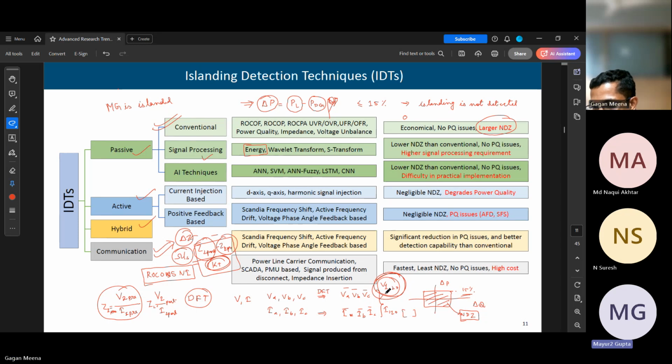Especially under frequency protection is there everywhere, because the grid has a plan for how to manage if there is a shortfall in generation. Automatic load shedding and all that will always be there, all based on under frequency. That includes the distribution system also, all discoms, distribution companies. So it will be there, I'm sure.